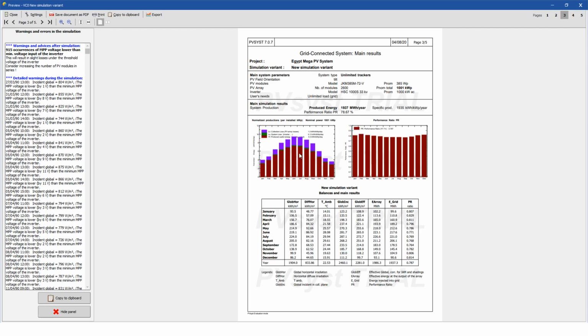Going to page number 3, here you'll find the data. For example, the performance ratio is 78%. It is usually between 70 to 90%, depending on the losses inside our system, shading effect, and different parameters used. But this one is acceptable. Here you will find the different months of the year, and the performance ratio differs from one month to another. Some months are high, some months are low, and here is a bar graph for it. You'll also find the energy of the array, for example here 102.2, and this is the energy going to the grid, 99.6 megawatt hour, at different times of the year.